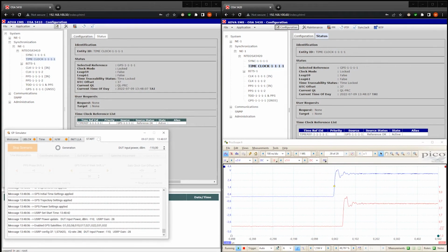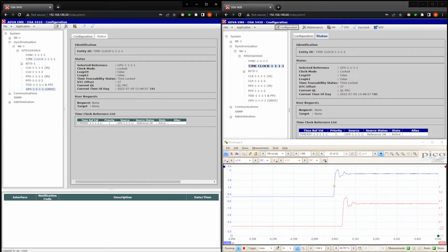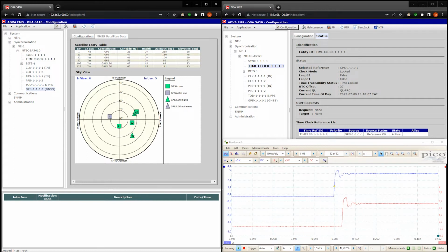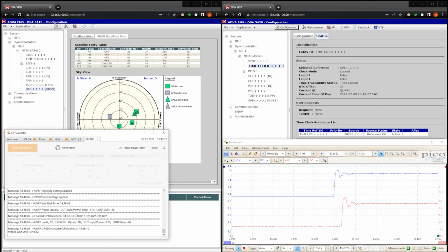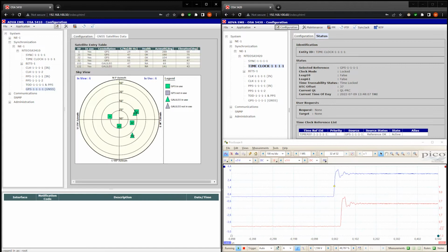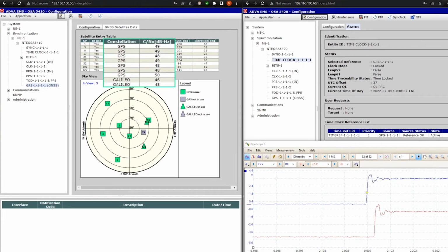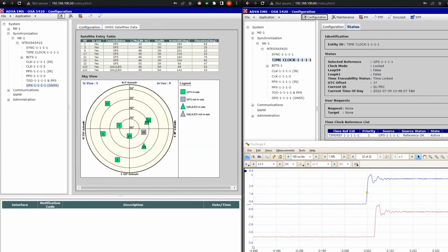I expect that after activation of the spoofer, the time saver will instantly switch to our fake signals, and it will not show any errors or even warnings. Why? Because in the first phase of the coherent or synchronous attack we generate a signal identical to the real one in all parameters. The signal is enabled, and as expected we see a great picture here. The GNSS receiver instantly accepted the spoofed signal. That's the coolest thing about the synchronized attack scenario.